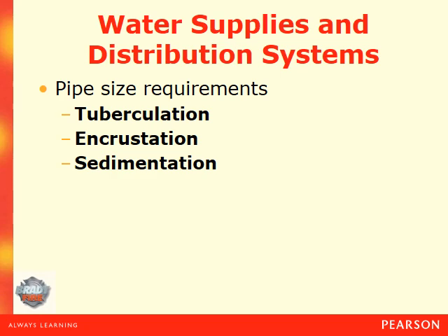Incrustation is very similar, as it is a collection of calcium and other hard water deposits that again start narrowing the circumference of the diameter of the pipe. And of course, sedimentation is the settlement of dirt and other impurities that make it into the water supply system, and then they end up encrusting the bottom of the pipes, again also shrinking the diameter. A lot of times the sedimentation occurs at the end of a line that only has water flow coming in from one side.